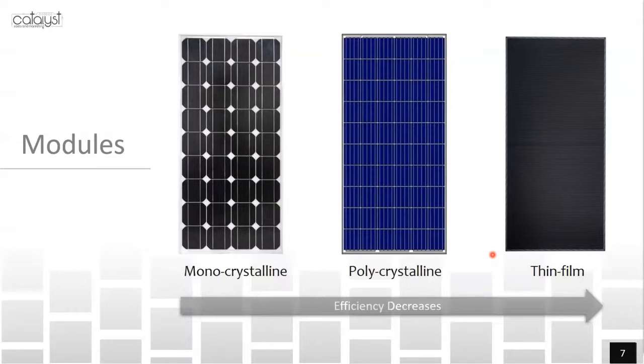What you'll use in all grid-tied systems is either mono or polycrystalline. And mono is the most efficient, but the most expensive. It's also the newer technology now. Pricing, because of economies of scale, has come down quite a bit. But mono is easy to tell by its characteristics. Mono has a black cell. If you can see here my laser pointer, you'll see that identification is pretty clear. And then polycrystalline is that blue cell.